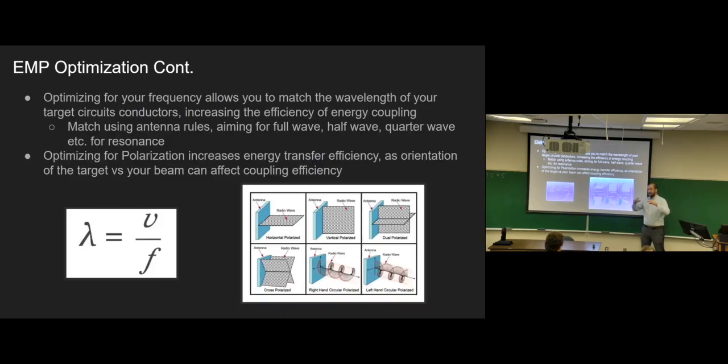And anything higher frequency, wavelength goes down. And the reason for that, by the way, that's the speed of light, so 3 times 10 to the 8th meters per second, whatever you like. Speed of light divided by frequency equals wavelength, which basically means as frequency goes up, wavelength goes down. So when we start talking things like cell phones, or let's say 5G, you're operating in like the 3 to 4 gigahertz band, and your wavelength's like 6 centimeters, 10 centimeters, starting to get shorter.